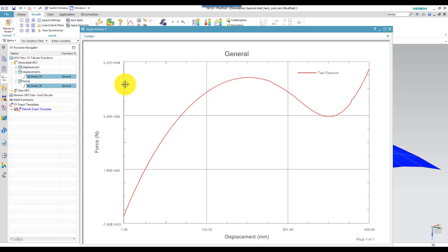I could also show you how you manipulate graphs in NX, but that will be another video. But we can state that displacement control is sufficient to capture the nonlinear snap-through behavior. In another video, I will post how you can run a snap-back behavior using force control in combination with arc length control.